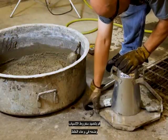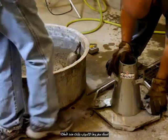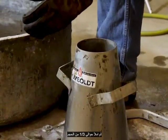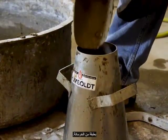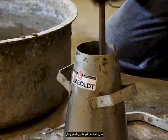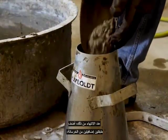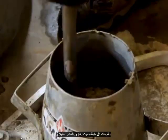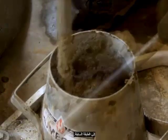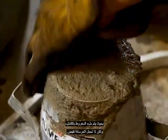Dampen the slump cone and place it in the mixing pan with the large diameter down. Hold the slump cone down firmly against the pan, and then fill about 1/3 of the volume with a layer of concrete. Tamp the layer with 25 strokes distributed uniformly over the cross-section of the cone. When you are finished, add 2 more layers of concrete, tamping each layer so that the rod penetrates slightly into the previous layer. Strike off the excess concrete so that the cone is completely filled but not overflowing.